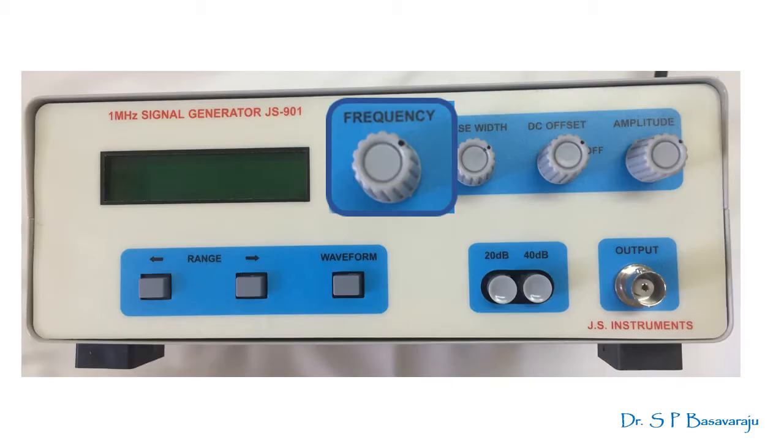The frequency variation should be started only after setting this current control knob at a particular initial position. Its position should be left untouched till the frequency variation studies are completed. Though it is suggested to keep the position of the knob at 50% of the maximum amplitude position, you may do it the way how you did in your regular class.